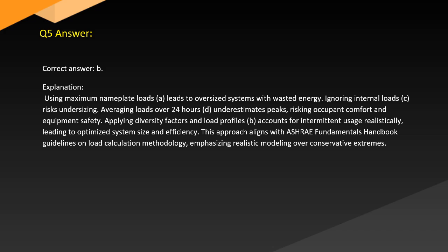Applying diversity factors and load profiles (B) accounts for intermittent usage realistically, leading to optimized system size and efficiency. This approach aligns with ASHRAE Fundamentals Handbook guidelines on load calculation methodology, emphasizing realistic modeling over conservative extremes.